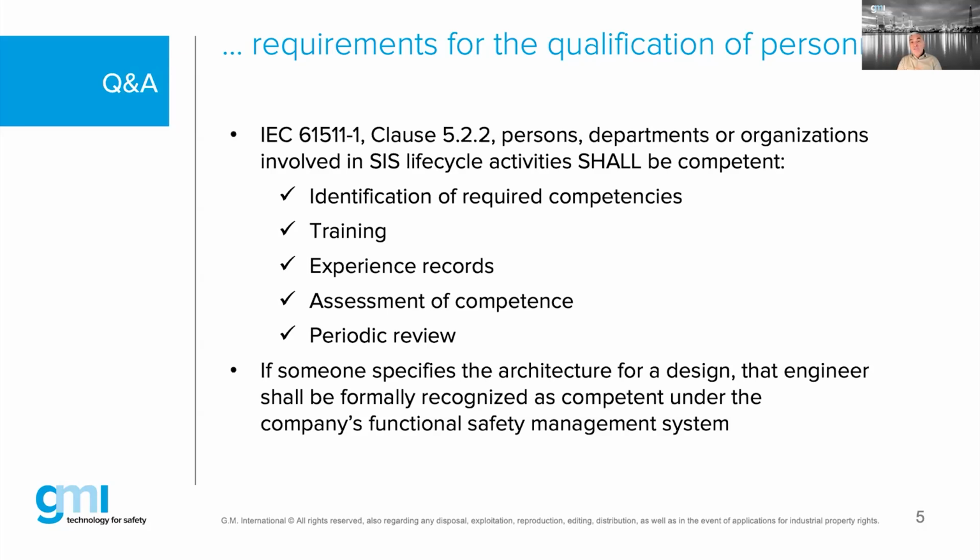That's why assessment of competency is a periodic requirement coming from the new edition 2, or the latest edition 2, which is new for 10 years now. But the latest edition 2 of the 61511 needs to prove competency by a periodic assessment, to prove that the people will maintain their competency in whatever activity they are responsible or accountable for. That's the periodic review, which was the last bullet.